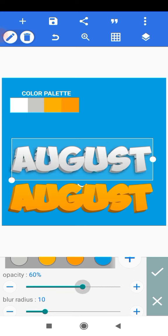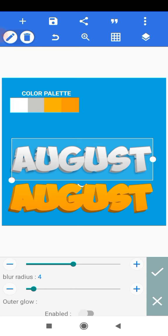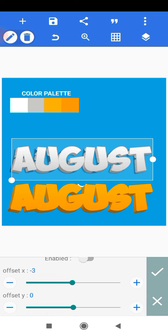And then I'll enable the shadow, and then I'll reduce the opacity all the way down to 50 percent, and I'll reduce the blur radius all the way down to 2. Then I'll head on to the offset on the x-axis, and I'll make it -3, and then the offset on the y-axis, I'll make it 6 pixels. So I'll click OK.